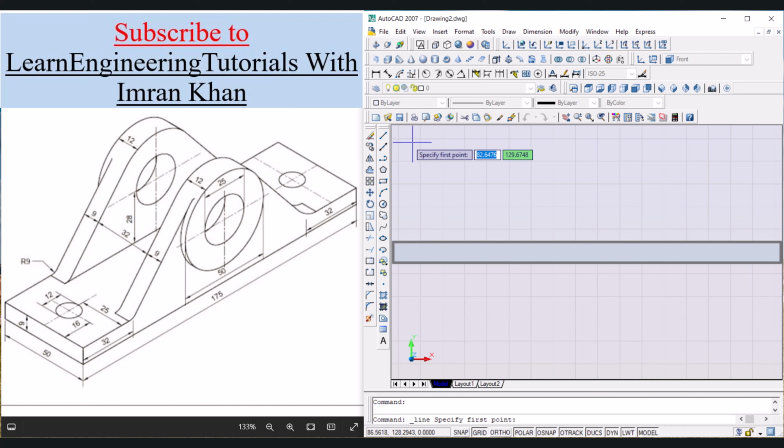Click on this line icon. Click on this middle point, move in the upward direction and give the value of 28, enter. Press enter again. Now click on circle, click on this end point and give the diameter of D, enter. 25, enter. Press enter again, bring the cursor over this end point, click and then give the diameter of 50,